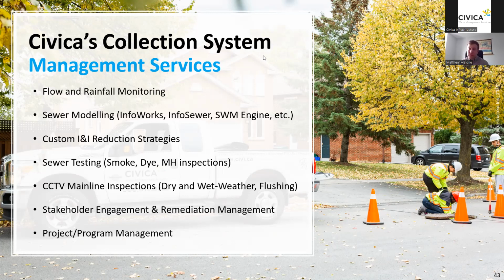And then from a flow perspective, most of the flow meters, at least the ones that have contact with the flow, so the area velocity meters that I talked about, most of the products we work with have temperature sensors in them as well. So it's built in. So if you want to know the temperature of the flows, again, depending on what product you use, a lot of them do have the ability, and it's a standard feature of monitoring temperatures of the flows.